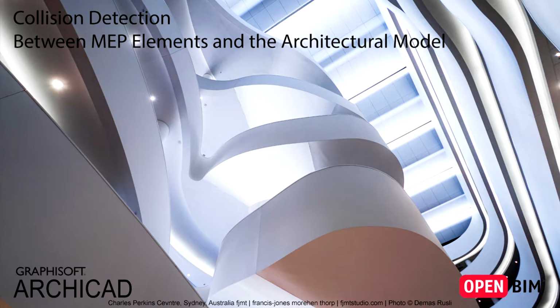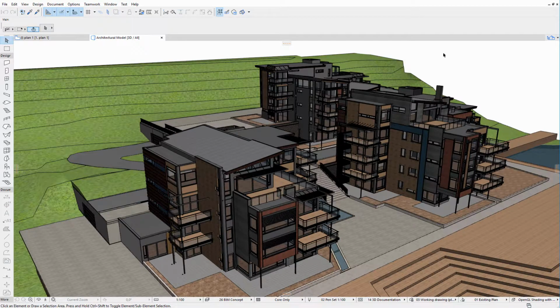This video presents an example for collision detection. We'll check to see if the hot-linked IFC MEP model collides with the architectural model. We can define two groups using element criteria sets and then perform collision detection for the two groups.